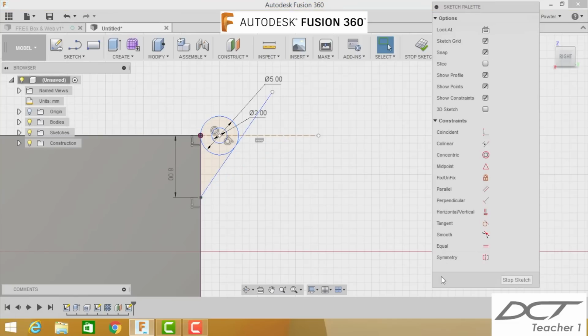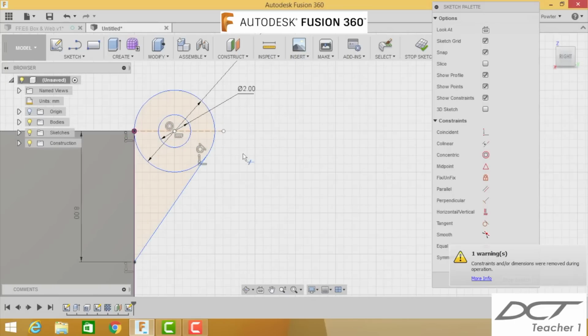Click the button there, and you can see now that I've snapped it and this tangential constraint has appeared. Now I just want to trim this little bit off here. So what you're going to press here, T for trim, you'll notice the trim tool comes up, and you're going to trim that, zoom in and get that little piece here. And this will just clean up the sketch a little bit. I'm going to trim that piece there as well. Okay, back into our home view.